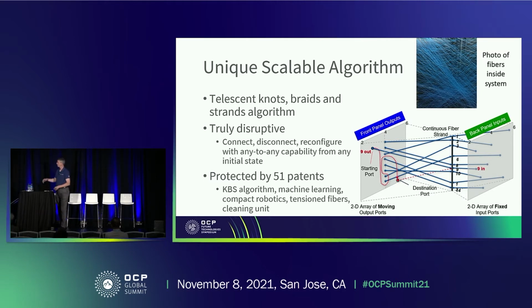Well, anyway, what you would see in the system is the robot will go down, pick up the fiber, and move it around the others. Since it is robotic, it takes about 1 minute to 4 minutes to make a reconnection. But once it makes that reconnection, it's low loss and latched. When the fiber finishes the connection, it also cleans in between the connection, so everything maintains consistent low loss performance throughout. It's also low power draw when the robot's in action, about 500 watts. When it's not being used, it's just a server that's running, so it's about 50 watts.